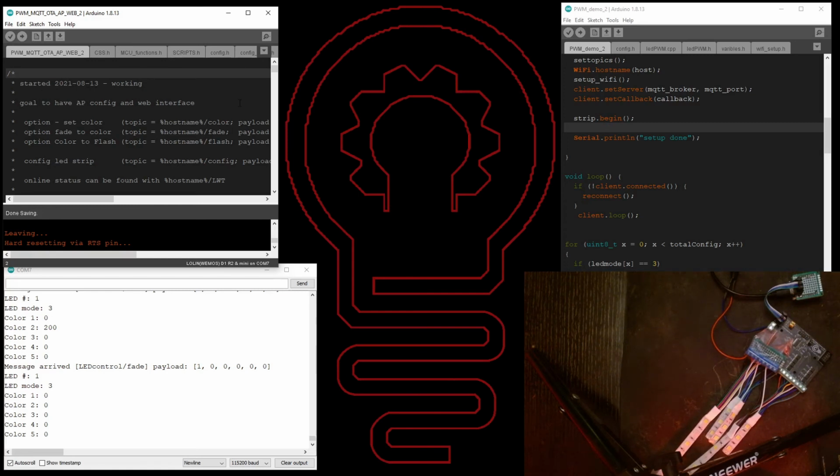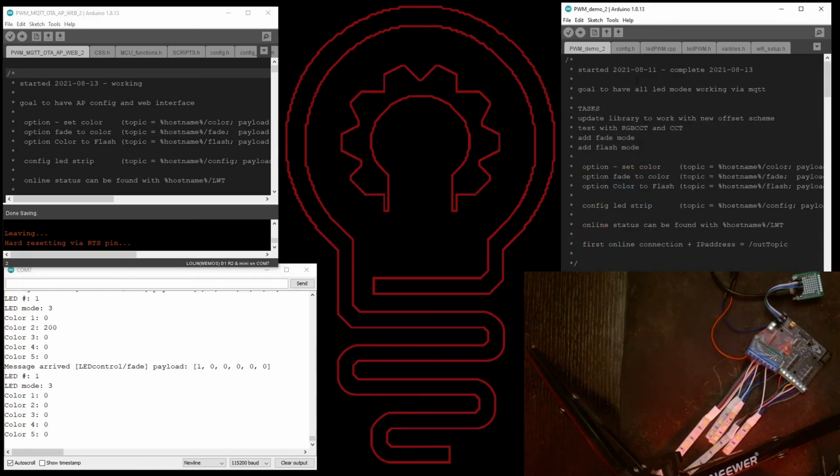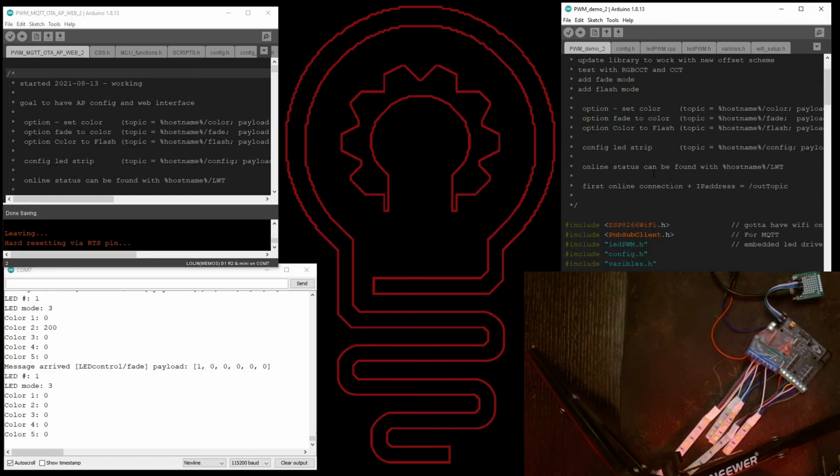You just flash it, connect to it on Wi-Fi, and you can set all your configuration, and it saves it in a JSON file on the device. The other one is only set up to run on an ESP8266. You'd have to change a few things to make it cross-compatible with an ESP32 or another device that you may want to use to control it.